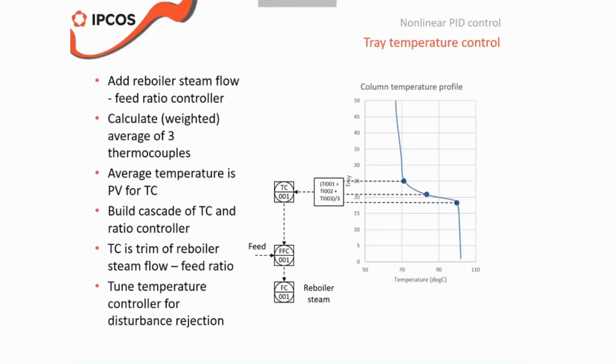Don't tune them as a steady state controller, like a temperature controller, but tune these very similar to a level controller, because basically that's what the temperature controller is trying to do here. It's balancing the temperature at set point.